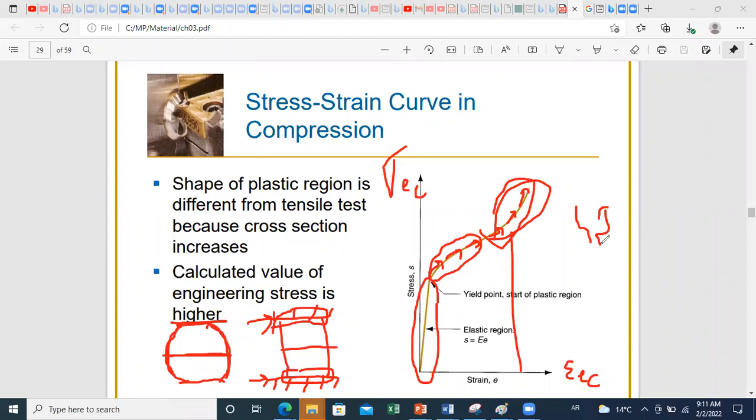And sometimes you can have collapse or buckling of fibers, which will result from the compression test and lead to failure. So this point can be defined in several ways. Other materials will fracture at their compressive strength limit if they deform irreversibly and you reach a very large deformation state, so that you consider that you will not proceed anymore with the compression test. Then we can define a certain amount of deformation that can be considered the limit of the compressive load.